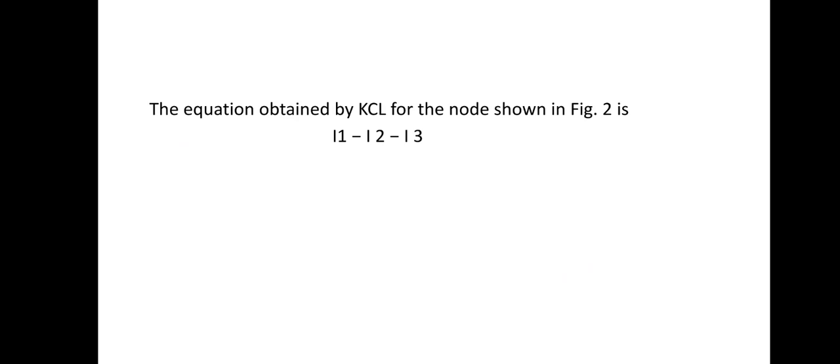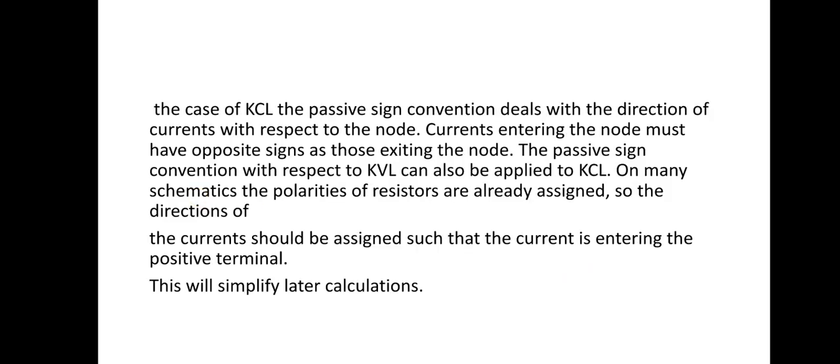Together with Ohm's law, Kirchhoff's voltage law and Kirchhoff's current law are essential in analyzing linear circuitry. Kirchhoff's laws deal with the voltage and current in the circuit. Ohm's law relates voltage, current and resistance to one another. These three laws apply to resistive circuits, where the only elements are voltage or current sources and resistors. Using the three laws, any resistance, current through, or voltage across a resistor can be found if any two are already known. The purpose of this report is to provide verification of these laws.